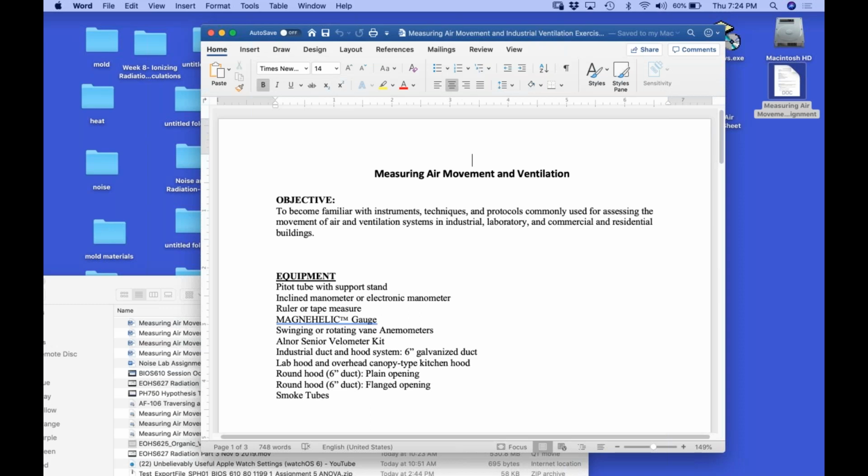Okay, so now, 0.42. Yeah, the first one was 0.30, the second one was 0.42. Okay, what am I reading now? 0.15. 0.14. So the difference between those two pressures, why is that happening? Because I'm taking the total pressure, subtracting the static pressure.